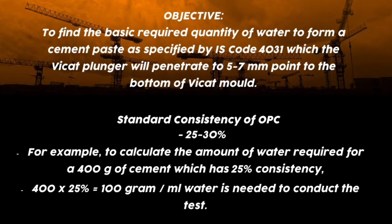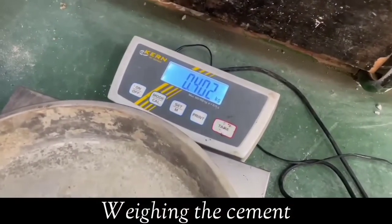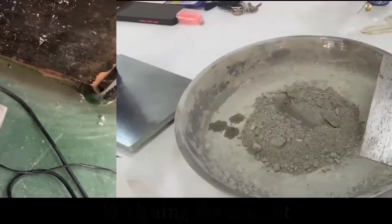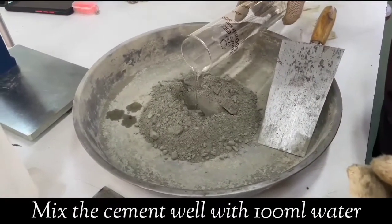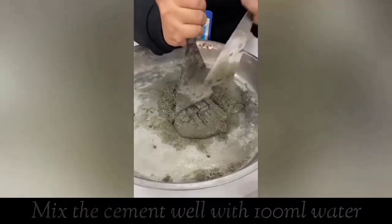For example, to calculate the amount of water required for 400 gram of cement which has 25% consistency, we multiply 400 gram of cement with 25%, so we get 100 gram or 100 milliliter. 100 milliliter of water is needed to conduct the test. First, 400 gram of cement was weighed on the weighing balance. Then 100 ml of water was added to the cement and mixed well for 3 until 5 minutes.